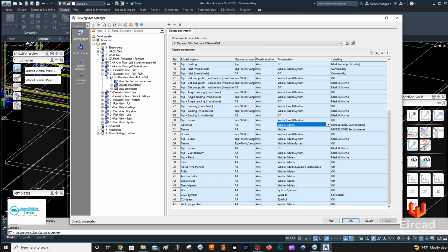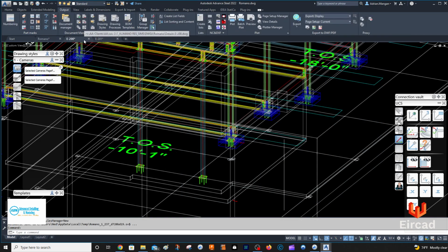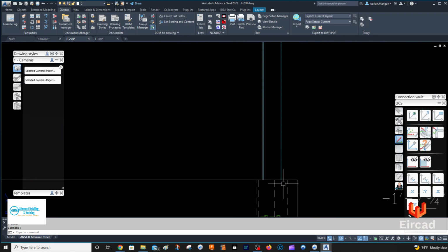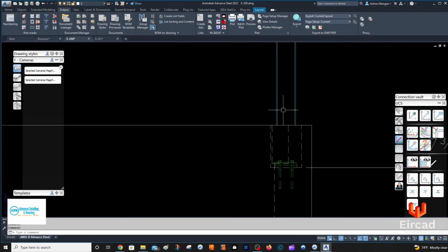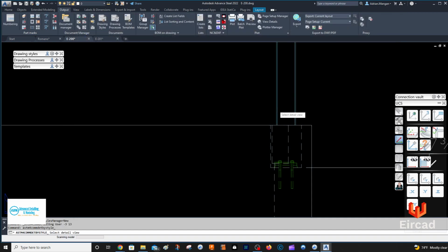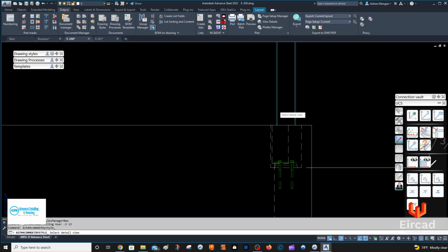Apply. Okay, now go back into the drawing, and these are going to be visible hidden. So what's going to happen is this will show up behind the wall. So go back in here, select the column, and we can now see the column behind the wall.